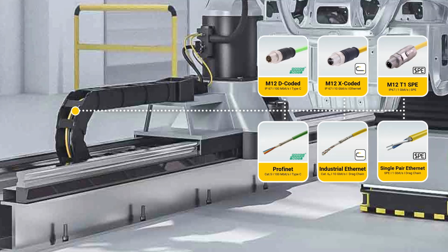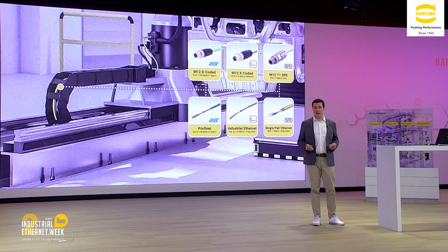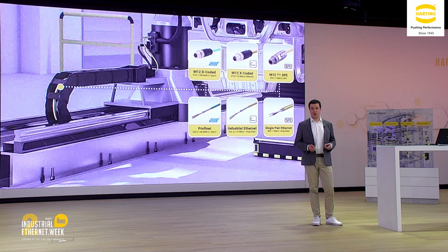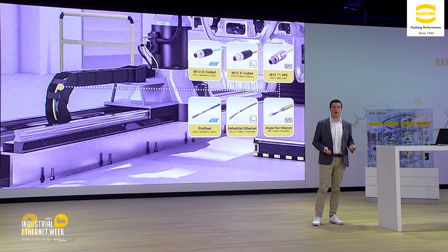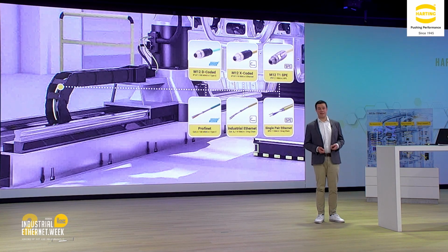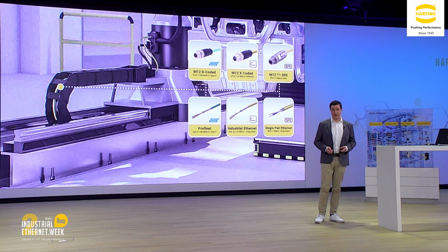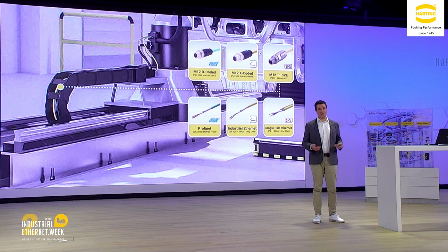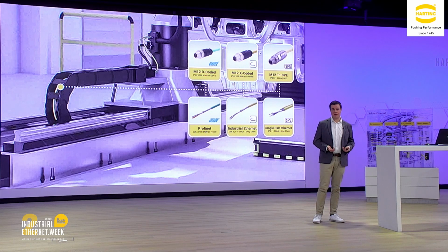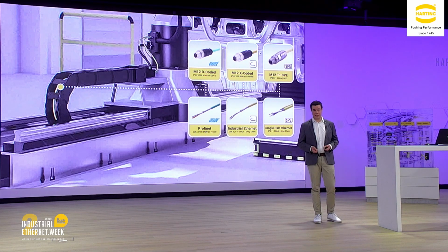Here we have a guided force on the cables, or bending, and the cable assemblies are also ready-made to buy with standard connectors for this kind of application, like the M12 D-coded for 4-pole Ethernet transmission, or the X-coded cable assemblies for Cat6a transmission performance, for example, for camera signals or something similar.